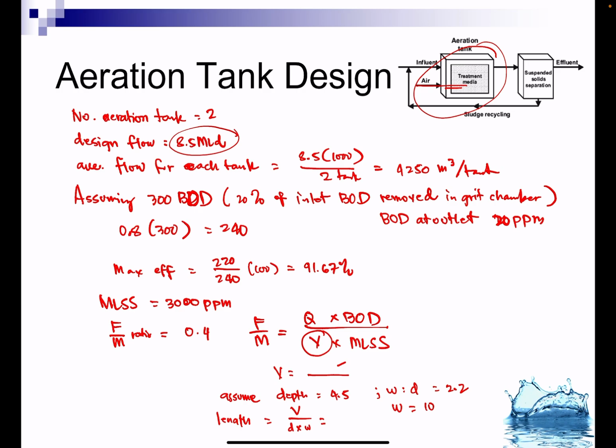So that's your length. Now, for us to check the aeration period or hydraulic retention time, your HRT is actually V over Q times 24 hours, since Q is per day. And HRT should always be between 3 to 6 hours only.